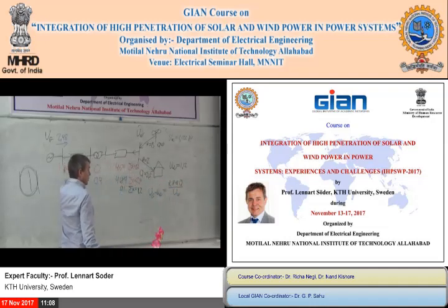If you have consumption, this is good, of course, because then you get a stronger grid. You don't get so much decrease because of the reactance. But if you have production, as we have here, then it's not the same thing, because you are consuming reactive power, and consuming reactive power is good for the voltage decrease. But the decreasing impact decreases, so to say, to make it complicated. So you don't decrease the voltage so much with the Q, and that is the reason why you get this.